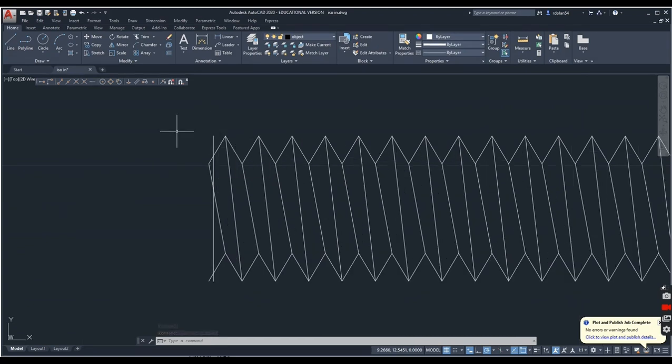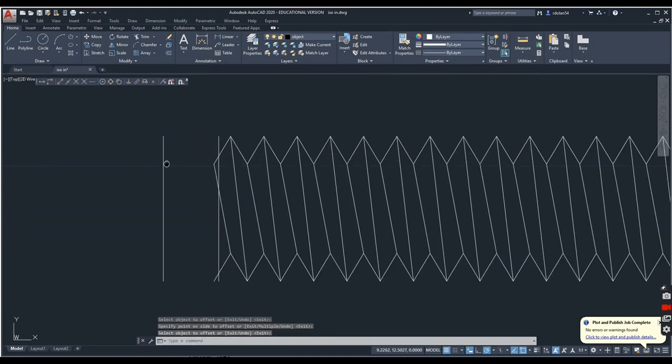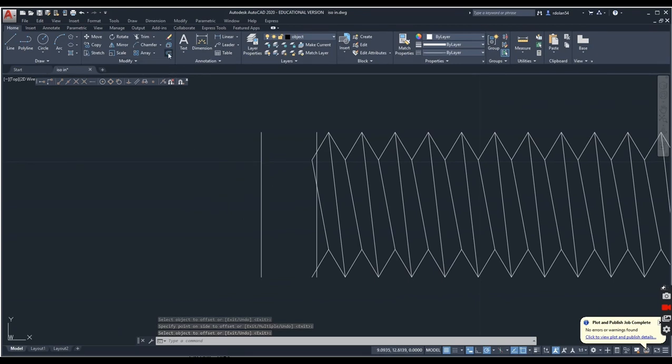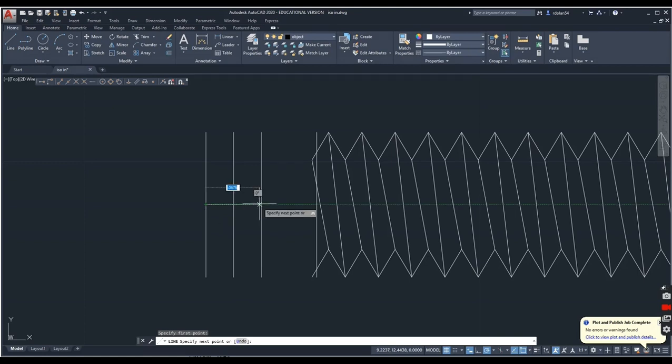Okay, I'm going to take this line now. I'm going to draw part of the shaft. I'm going to draw it as a break. So I'm going to offset from here about 2 threads or a little bit less. So I'm going to make that 0.070 from here to here. Then I'm going to offset 0.35, and that's just a number I came up with because I know it's going to look good. You have to play around with them and find out what your number should be. I'm going to draw a line from the midpoint here to the midpoint here.